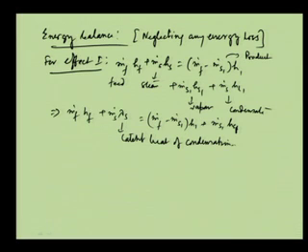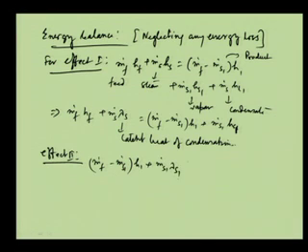Now, comes effect 2. For effect 2, it is m dot f minus m dot s 1 into h 1 plus m dot s 1 lambda s 1, which will be equal to m dot f minus m dot s 1 minus m dot s 2 into h 2 plus m dot s 2 h s 2, exactly the similar way.